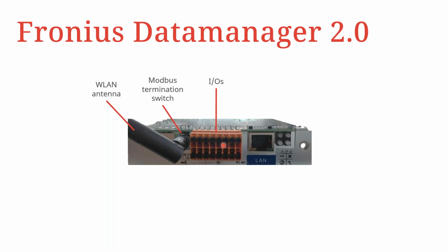Next up are our input and output ports that can be used for programming other devices, energy management in short. And then we have our LAN bus, which is the Modbus TCP. And then, of course, we have the IP switch, which is also another DIL switch that is located just above the status LEDs. The status LEDs play a very, very important role, especially for the installer or the client, for easy notification of the status of the inverter.